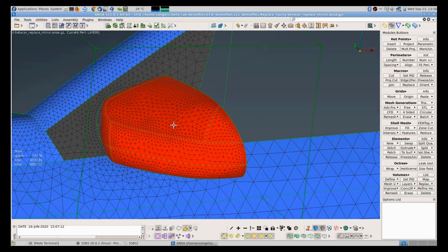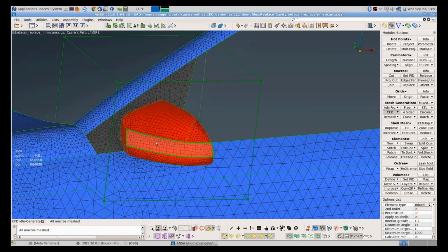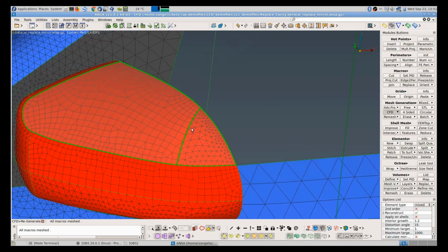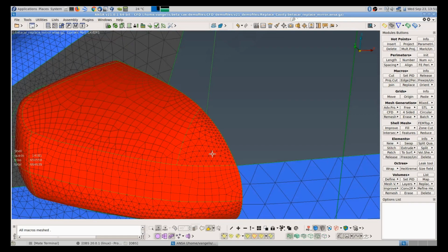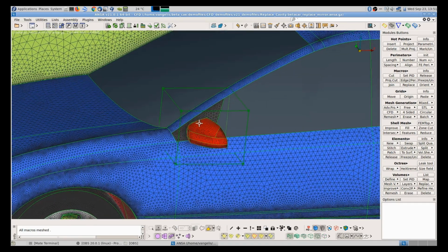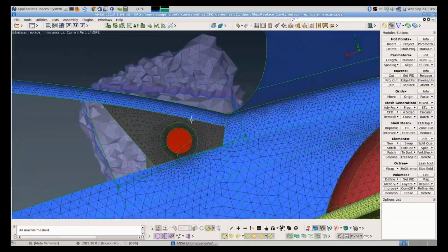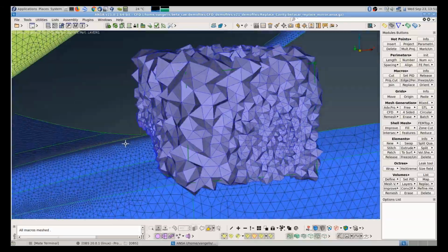So now I'm free to make any changes on my surface mesh, right? For example, I can switch to mixed mesh, right? Okay, so I made a change on the surface mesh. I can also replace geometry as well as before, right? There's no restriction to that. My cavity is always there, so I can make any change in that space.